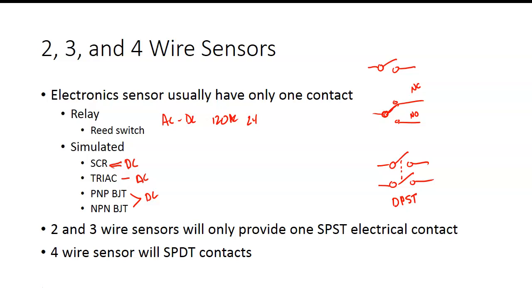The biggest problem we have with relays is their speed of operation. They don't operate extremely fast. Take motor control: you told a relay to energize, it didn't energize just like that, because it's got to generate that magnetic field and pull that armature down and make contact, right? And plus, they're electromechanical devices. The big advantage is that it doesn't determine what type of voltage you apply to the switch itself.